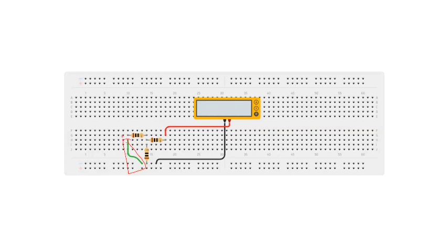Earlier, these two terminals had the voltage supply connected to them, but now we have short circuited those terminals, meaning we have replaced our voltage source with a short circuit, and now we have taken a multimeter which is set to measure resistance. All right, so whatever the value of resistance is will appear on the multimeter.